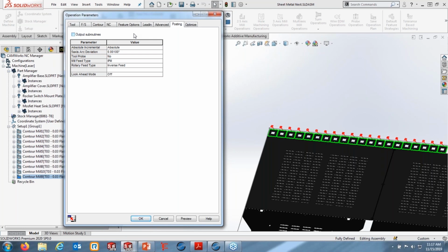We always used to have that, but it was always on an individual part. So in an assembly like this, you'd turn it on and it would be on for everything. Or it would be on for a linear pattern in a part file, for example. If you've got something like these slots and you pattern them, so you program one and pattern it across here, you'd be able to get the M98 capability for doing that. But now it's on an operation by operation basis.